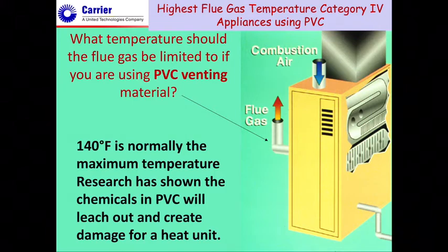So that creates a little bit of a problem for us for most heating units. So you got to be really careful with that. In some situations, certain appliances would put a condensate fitting leaving the boiler or leaving a system where, if they would, all the condensate would roll back into a T and then drain out before it got into the boiler.